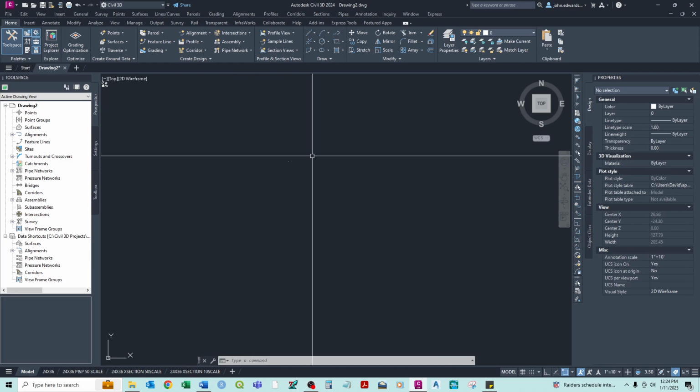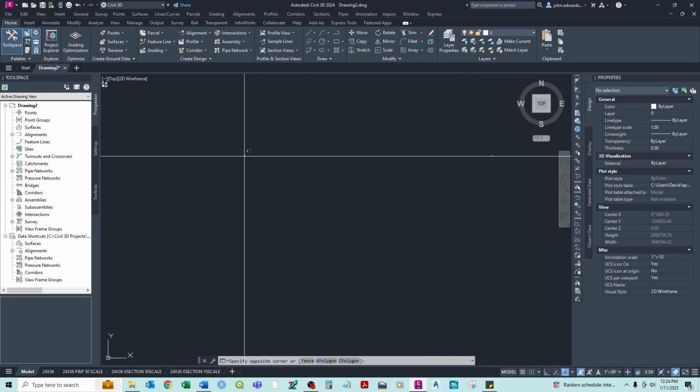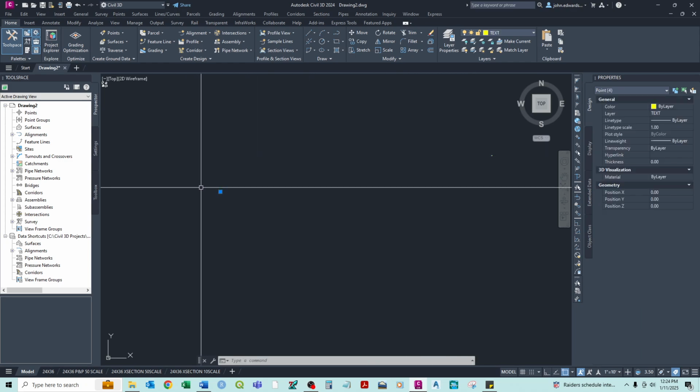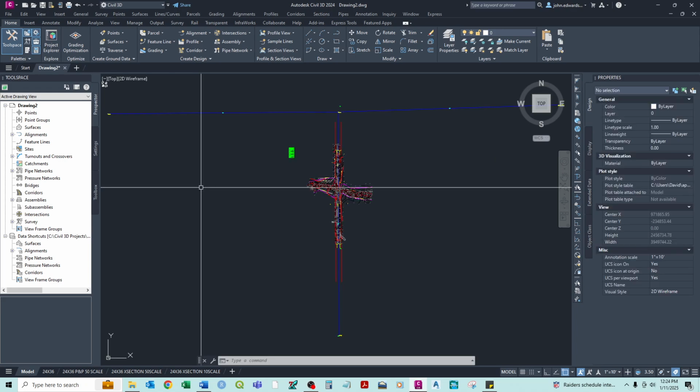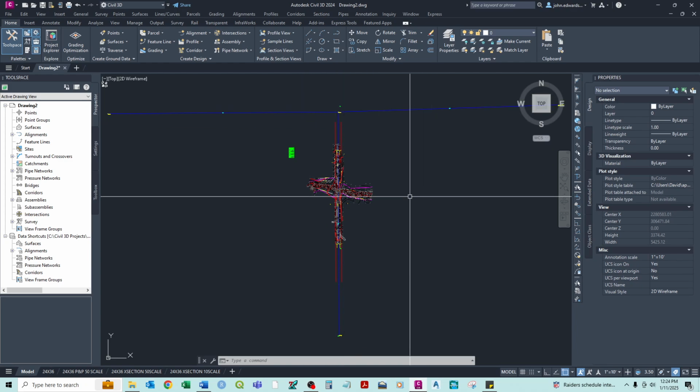So when you zoom extents, it pulls the entire extent between that point and your survey. So I just go in and delete these points because they're not relevant. And now if we rezoom extents, we're back to our survey area. So that's just kind of a unique feature when we get our surveys, it's not a big deal, but it's probably not a standard thing across the board.